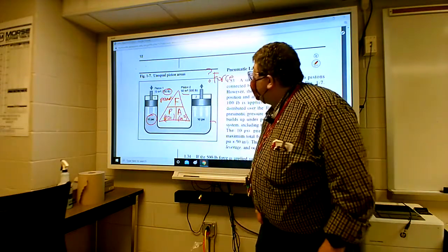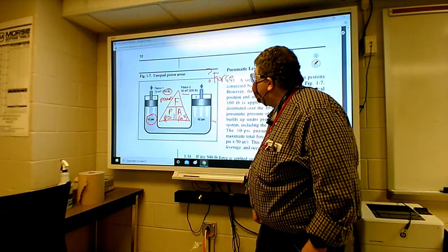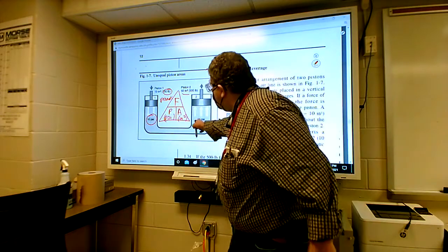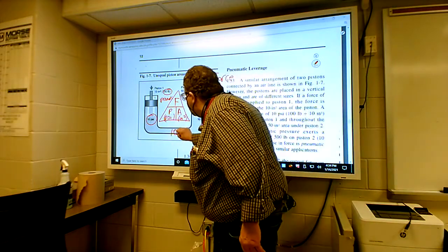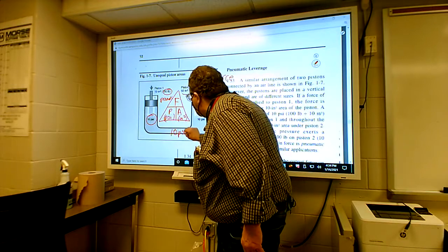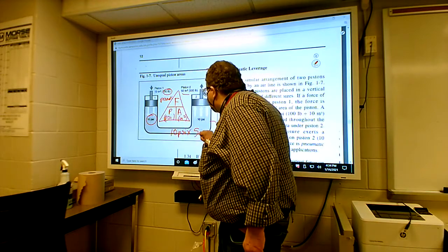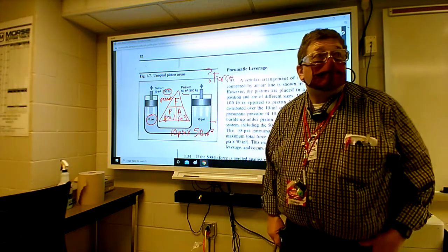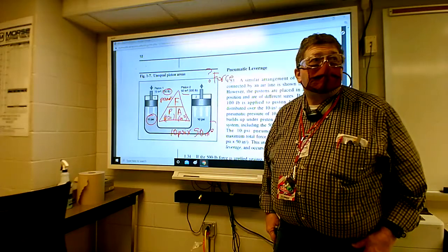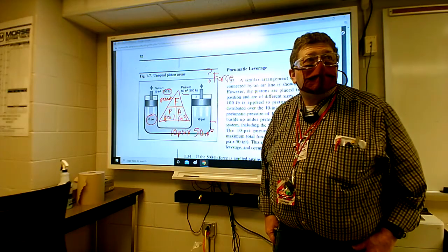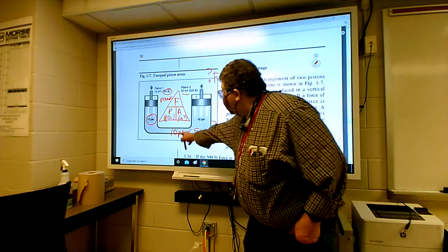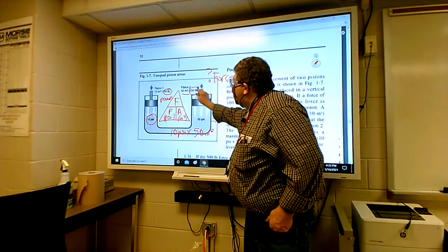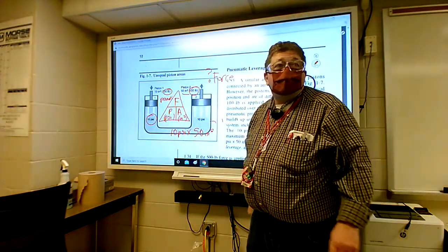Look, you got 10 psi times 50 square inches, right? Well, you multiply. What's 10 times 50? 500, yeah. So it would lift a 500-pound weight.